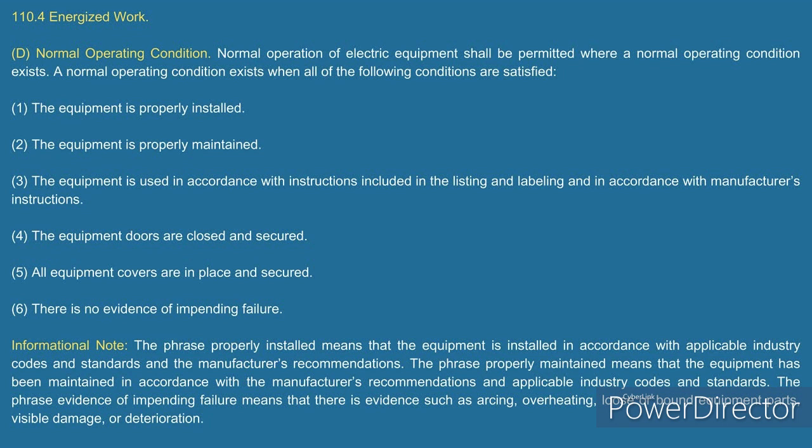You've heard me say this over and over: the NEC is an installation manual. I've said that so many times. You're installing by the National Electrical Code, and then there could be other standards you may need to look at. If you're doing fire alarms, you may need to look at NFPA 72. Maybe I have some custom-made equipment. Not only am I tying it in with UL standards, but I'm tying it in with NFPA 79. You see what I'm saying?